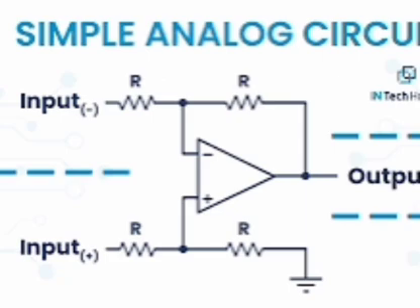It is current control device. Its input impedance is low and output impedance is high. Thermal stability is less because of leakage current or reverse saturation current. In transistor, all the major currents are diffusion currents. Base current is recombination current.